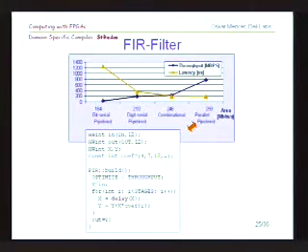And I've solved the problems that are really hard to solve for the compiler, which is how to map the variables onto the particular features of my architecture. I let the compiler do things like scheduling and building of the data flow graph, shifting between different sizes of operations, putting everything together the way that makes actual sense, and get me the resulting circuit.